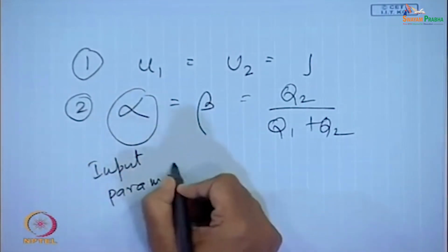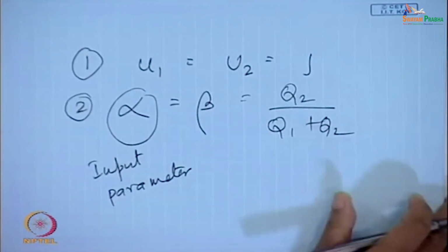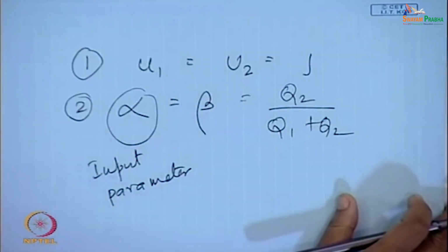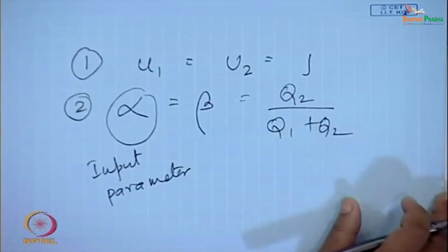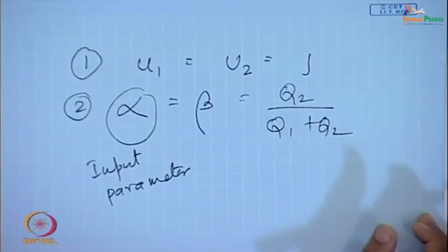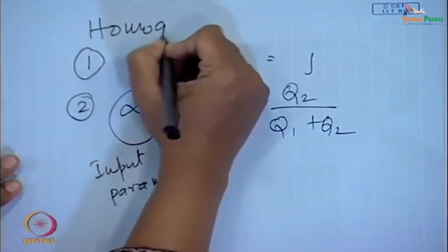If we know the flow rates of the two phases, which is very easy, you just have two rotameters or any particular flow meter, you can find out the inlet flow rates. Moment you know the inlet flow rates, we can find out alpha. So now under such circumstances, I will just put the heading here, although you know what I am teaching.